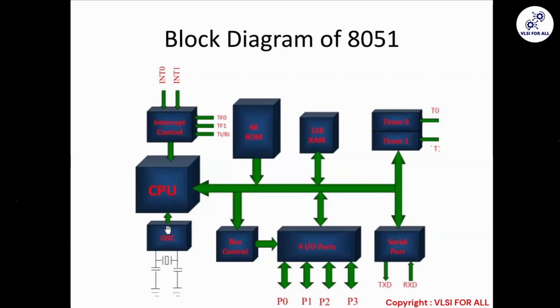This is the clock frequency, whereas the CPU works at machine frequency. The machine frequency will be lesser than the clock frequency. We'll deal with it. So the clock frequency is getting divided, acting as the machine frequency, and with that machine frequency our CPU is doing arithmetic and logical operations.